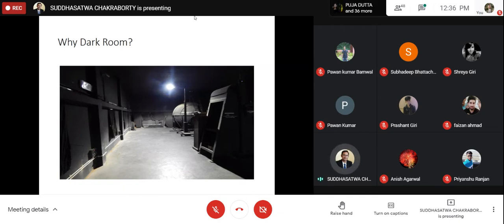So keeping that in mind, being a designer, being a scientist who is measuring the data, we will always provide data which is for the direct lights. Now your surface reflection, the parametric dimension of the room, that will vary. So that's why the designer who is going to do a design, he will be taking care of those issues. So that's why this is a standard and very important practice while we are performing any photometric measurements, that should be done only on the basis of the direct lights, because the reflected light will be calculated separately based upon the different situation.